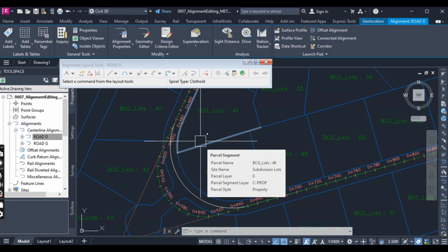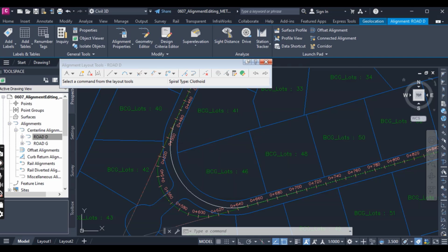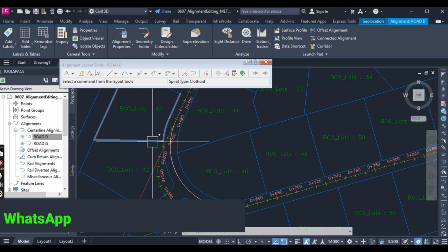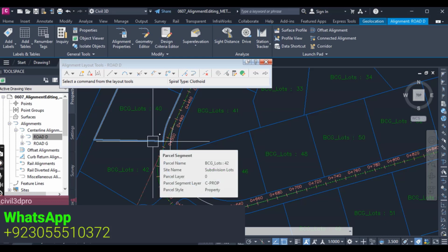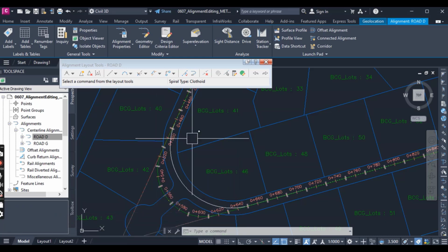Grip editing is commonly used to place the line and curve of an alignment in an approximate working location, but then you use the tabular view in panorama to make the values more reasonable. For example, to change a radius of 292.56 to 300, which is a round figure. Also note that in this part of the exercise, when you change the radius, the violations of the design checks were cleared for the curves, providing feedback that you meet the design requirement.